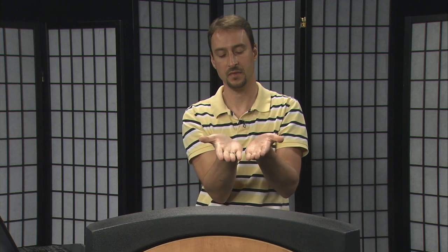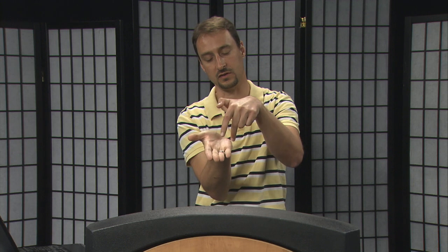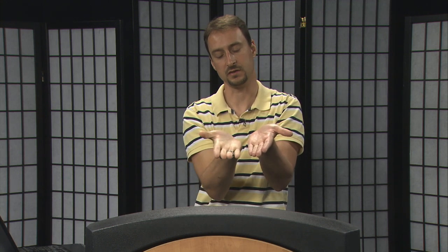But the normal vector from this cell is exactly the opposite from the normal vector on this cell. And so what I would like to do, instead of visiting this cell and this face once and only computing the contributions here, and then going to this cell and computing contributions on this face, is this: every time I visit one cell, I would like to compute 1/2 of the contribution from this cell plus 1/2 of the contribution from the neighboring cell.